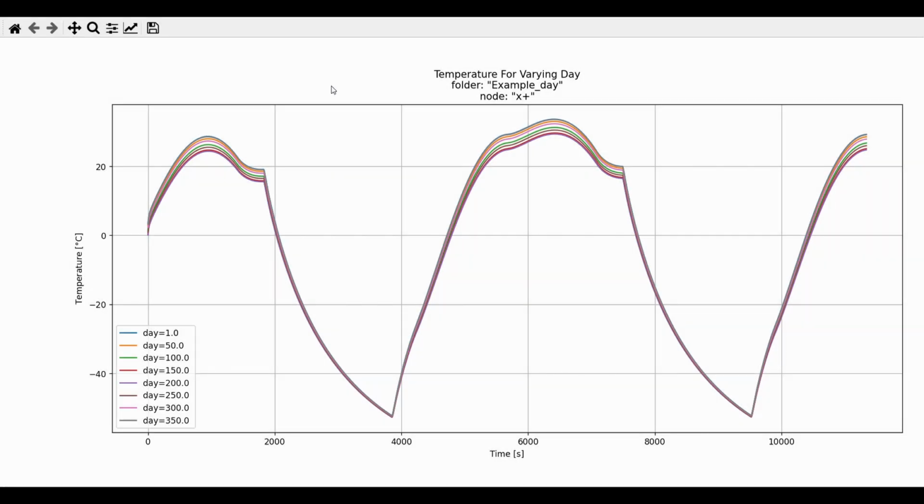Another plot which is associated to the previous plot is this one, where once again it shows for different input variables what the results are, but instead of showing the minimum, mean, and maximum temperatures of the whole model throughout the whole orbit, you get actually time varying data. So now on the x-axis we have time again, and on the y-axis it's temperature, and we see what happens to the temperature throughout the whole orbit. So this gives a little bit more data than the other one.